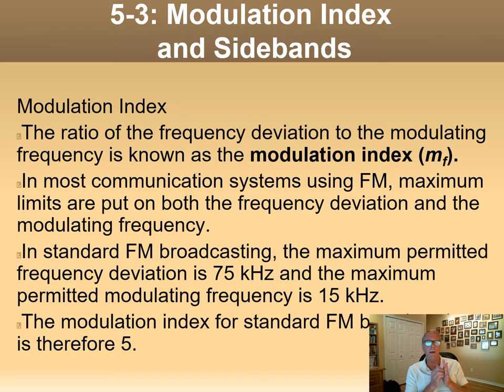So what if you had a 100 megahertz carrier and you wanted to modulate that with a megahertz? Well, you'd get 101 megahertz, and then 100 megahertz minus a megahertz. So that's a pretty wide bandwidth. That's 2 megahertz at least, plus all the other sidebands that come along with it. You can't do that and preserve spectrum.